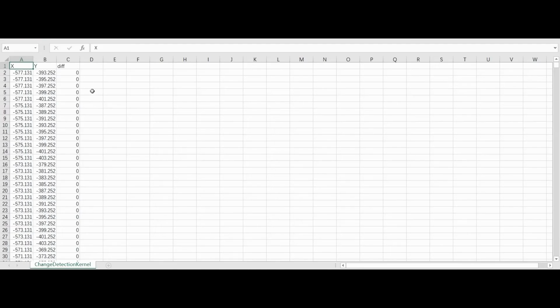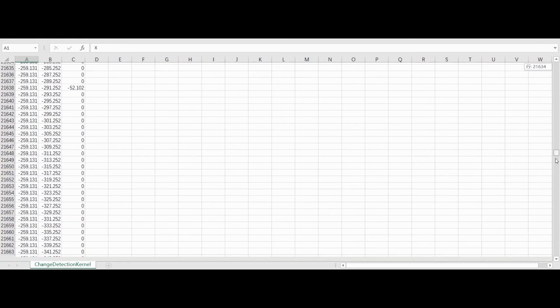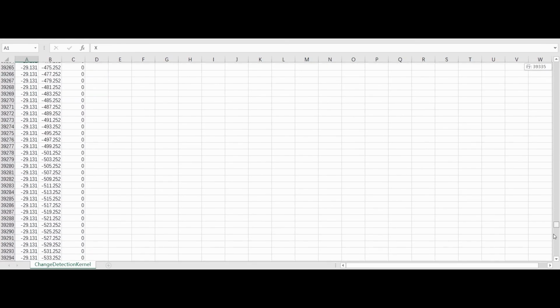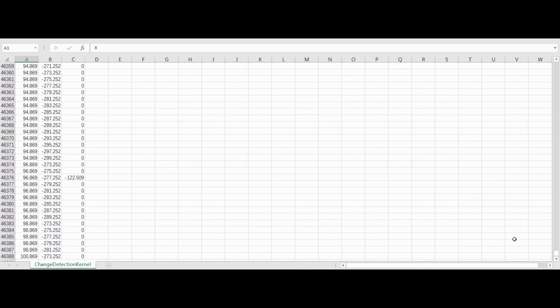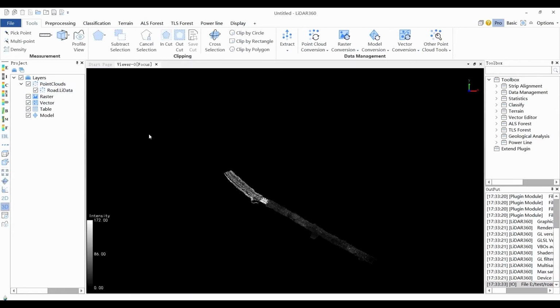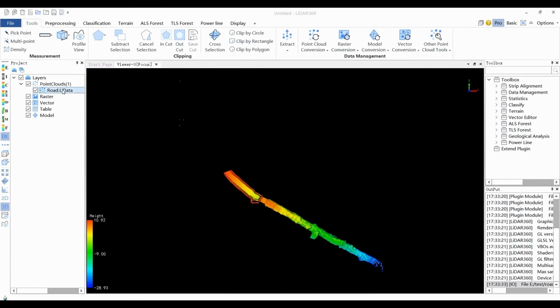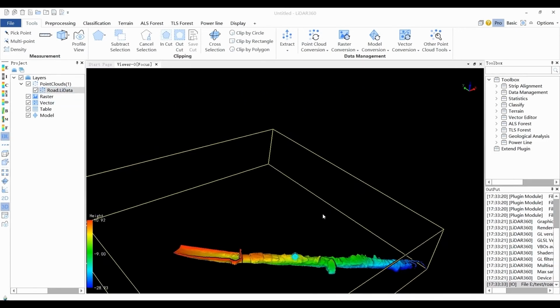This section analysis module is aimed at road cross-sections and tunnel cross-sections and mainly solves problems such as the design of reference cross-section lines based on point cloud and model data. This function is based on the actual measurement data to obtain the measurement section of each location or the real topographic undulation. It can edit and manage the measurement section. Finally, output the information of each section and generate the over-under excavation report.